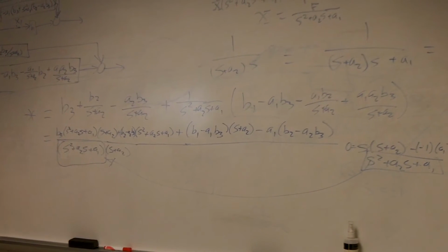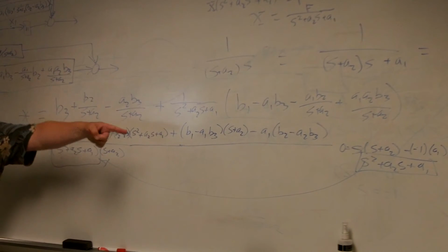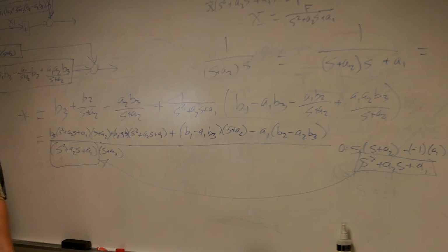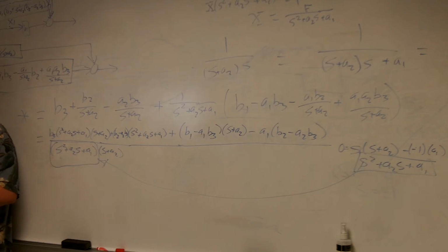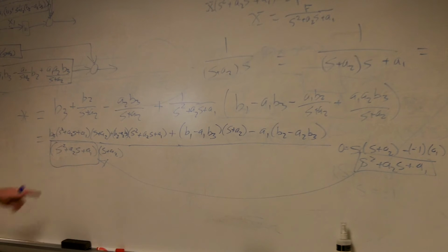So that's called the characteristic equation. The characteristic equation of your matrix, which is what gives you your eigenvalues, gives you the poles. It's identical. Therefore, the eigenvalues are the poles. They satisfy the same equation. That's the big thing I wanted you to see. If you see that, you've got the big lump of this. Which means everything you had to do with stability was centered around finding those.